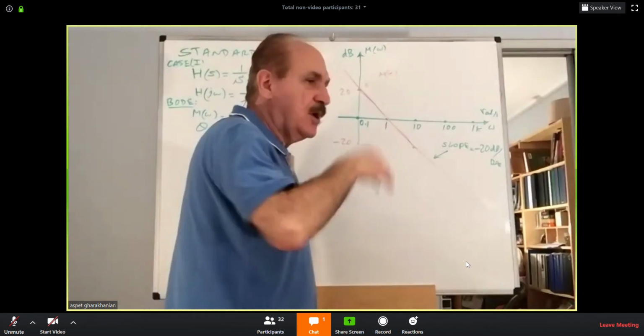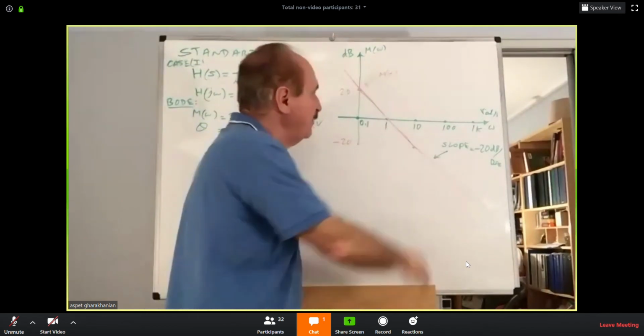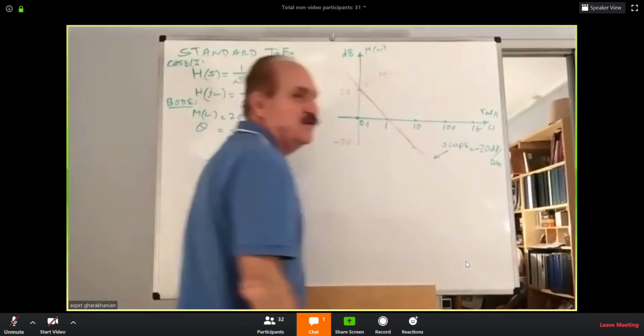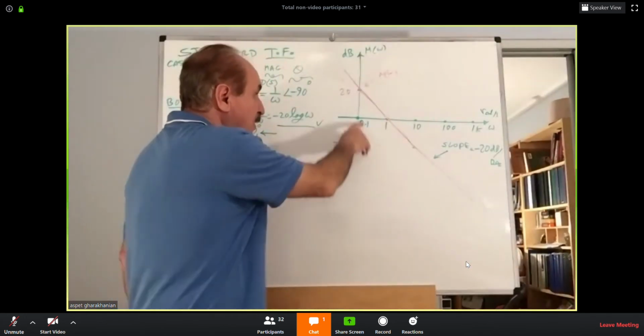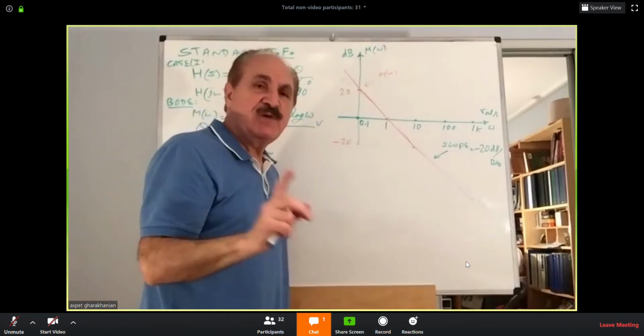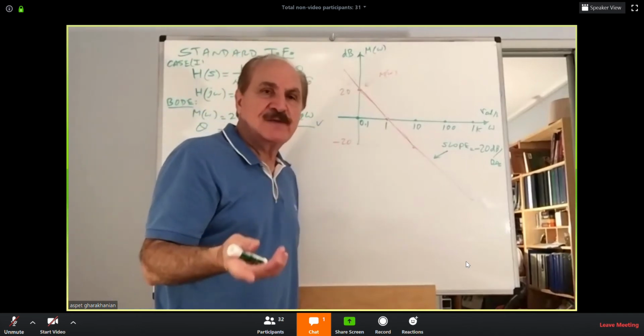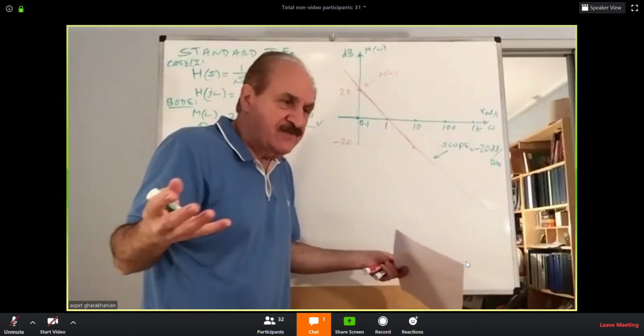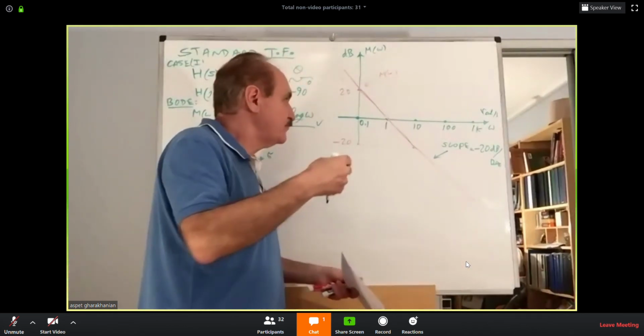So the gain drops at a constant rate of 20 dB all the way down, no matter how high you go in frequency. Negative dBs speak of numbers that are less than 1. Remember, logs of fractions are negative because a fraction is less than 1.